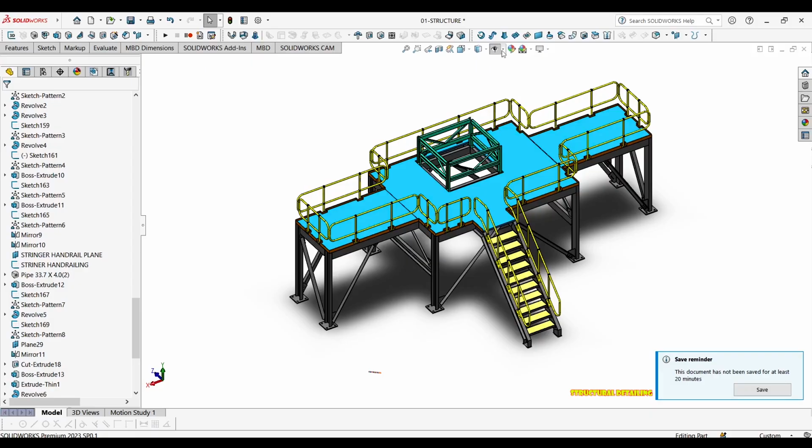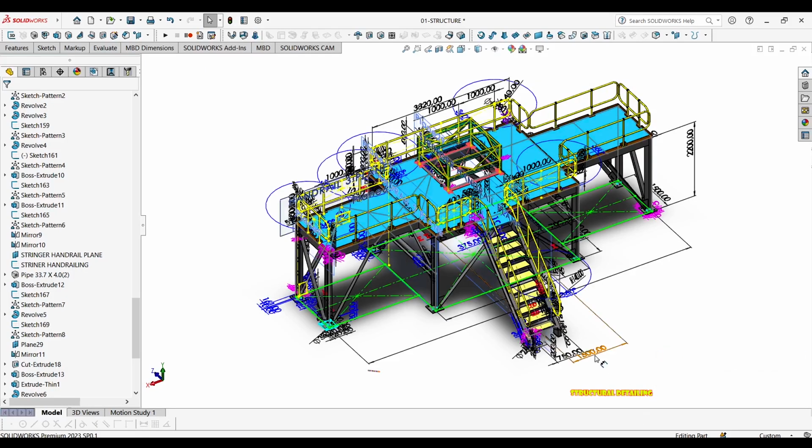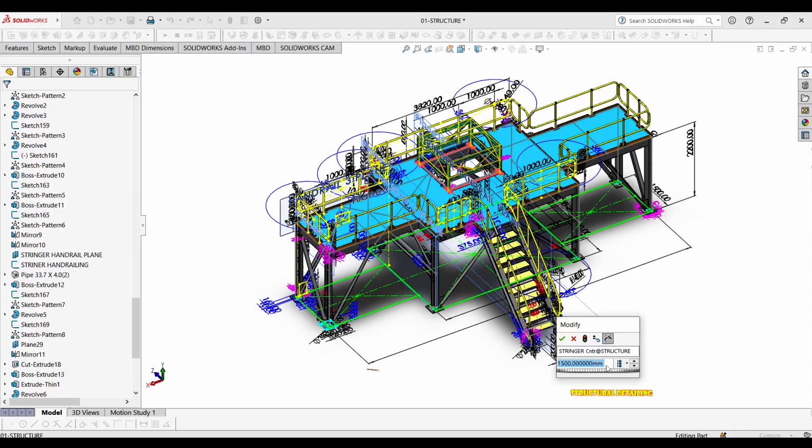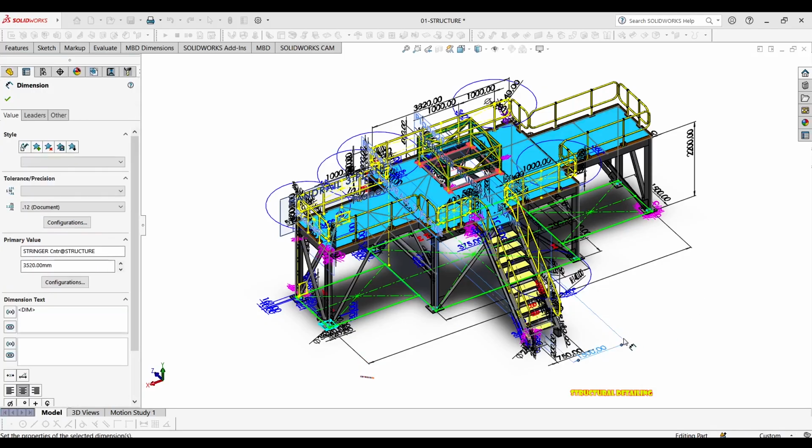I'm gonna plus 500 there and just put it to 2000. Make it 2000. I think I liked it there. Or 2020. So you see, guys, you don't even have to say plus here. On the dimension, you can just type the number. It's like the program knows that if there's no negative sign in front of whatever you just added, it's an addition. So yes, 2020 is actually where the center is. I did measure it, so I'm gonna say 2020 there.